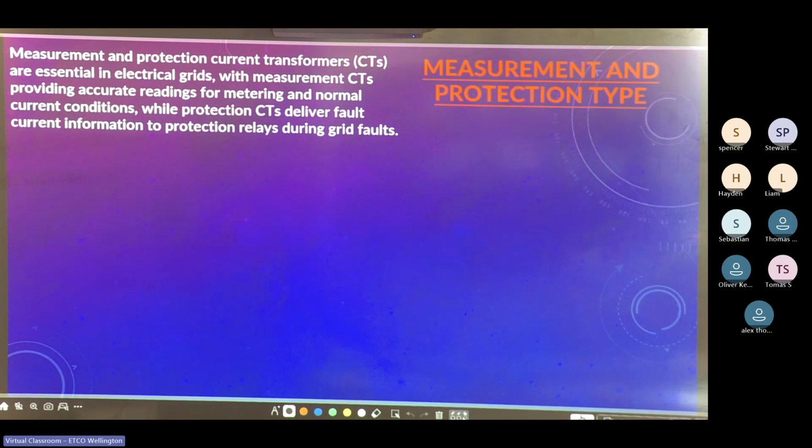This way, the relays don't have to be necessarily built to handle the massive high current or high voltage of the load or the transmission, but they can control the large contacts of the switch or the contactor for the high voltage or high current. Does that make sense to you guys? The contactor analogy?